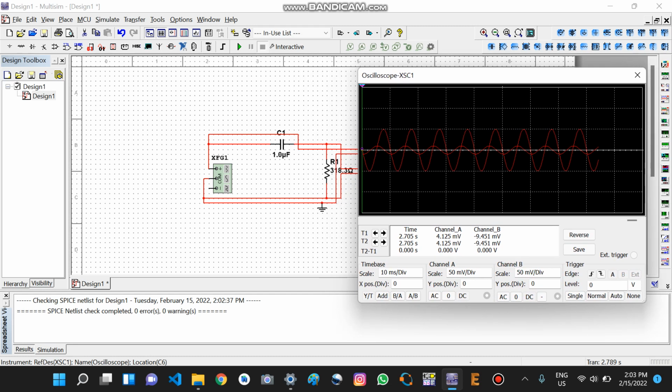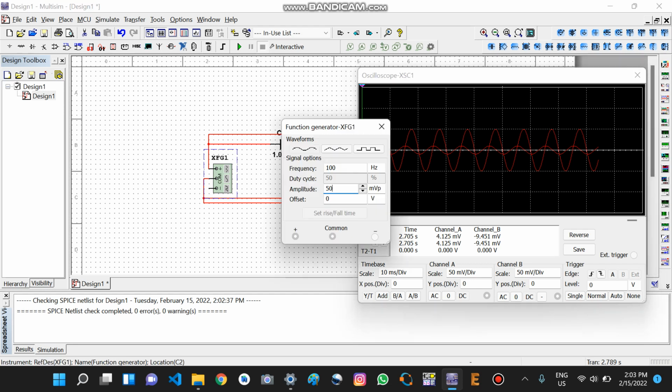It means the capacitance is not allowing most of the voltage. It is taking most of the voltage, while the resistor gets little. Now as the frequency increases beyond 500 Hz, you can see how the high pass filter reacts. As of now we have tested against 100 Hz.